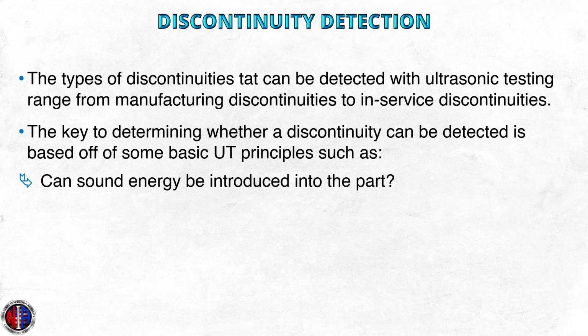If the part has a rough surface finish, sound energy may be reflected off of the surface, again limiting the ability to perform inspections. Complex geometries can also be a limiting factor in being able to get sound waves to the area of interest.